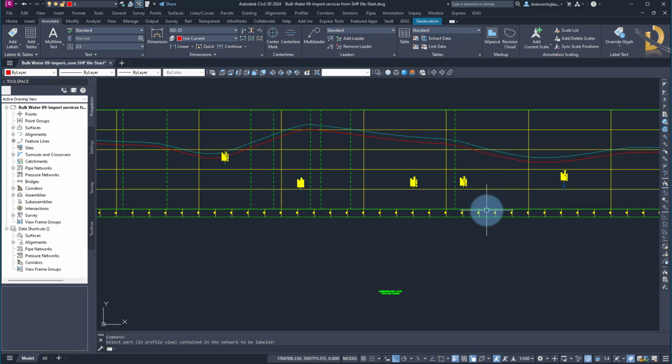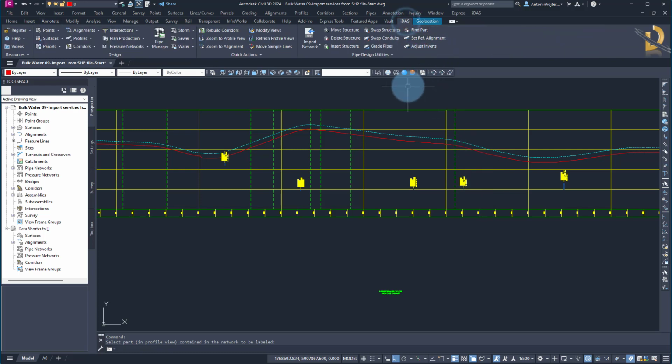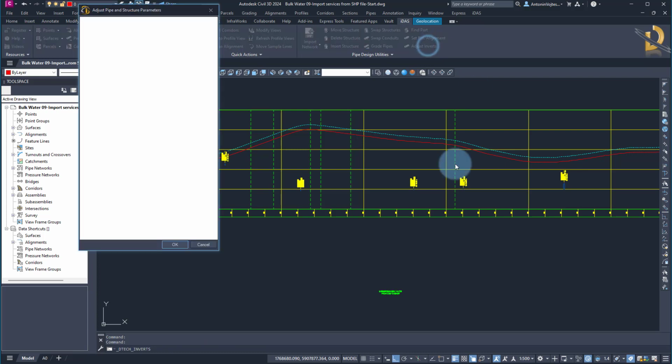If it was a gas pipeline or if it was, let's say, an electrical line, low voltage or high voltage, let's say if it is 0.8 or 0.6 meters below ground, then you can move the entire network. With a stormwater network or sewer network, it is more difficult because you have no idea how deep the pipe is, because it can be anything, let's say, between minimum cover and the maximum cover. But in this case, I will assume, and I know it's not right, but I will assume that all of them are, let's say, covered at 1.4.